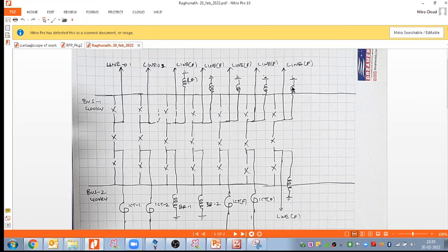Two things: one is I did not include the breaker, and I think I did not include the NGR that is required. Correct. So you have to include the breaker, that is fine, but do not put the earthing directly here. You put the NGR first and then you go to the earthing. Yes. And before the reactor, on both sides, put the LA.